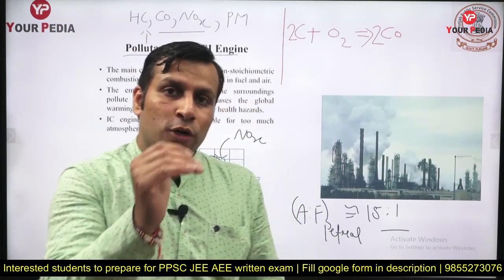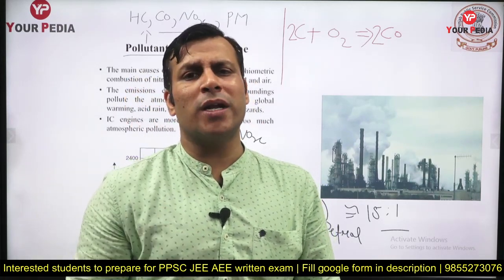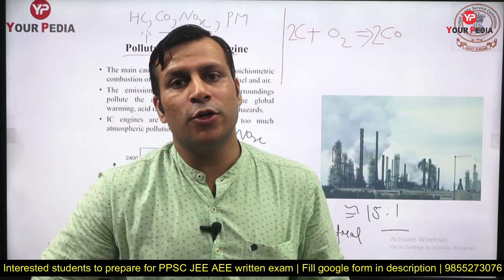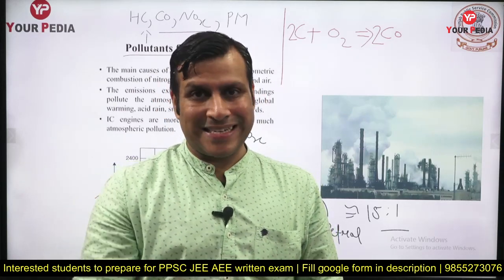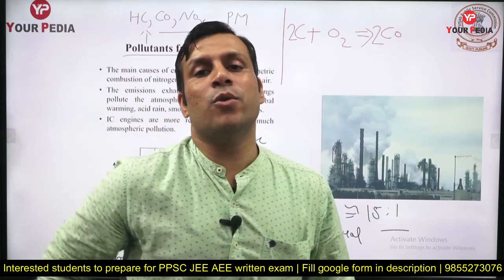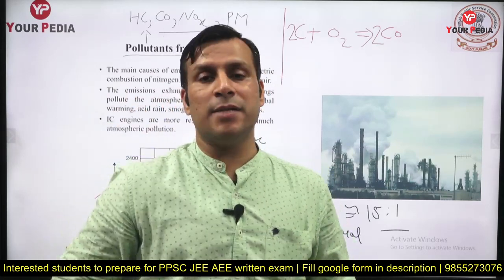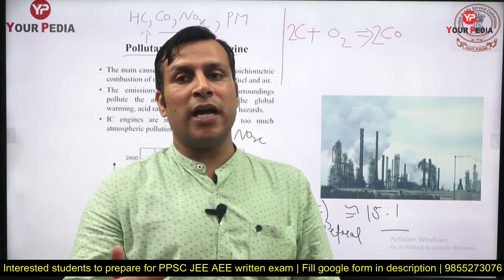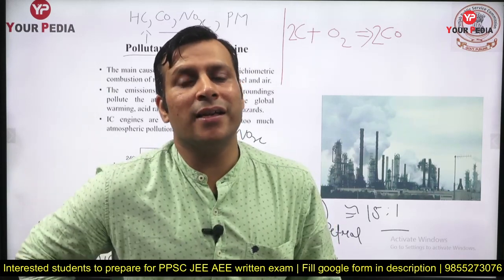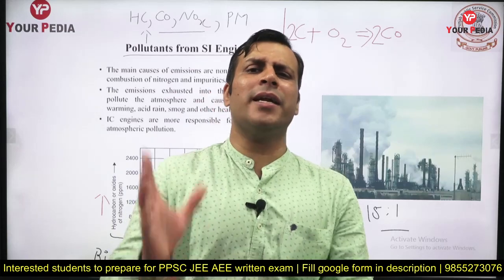So if you are able to reduce the engine temperature, if you are using a lower compression ratio, the NOx emission is going to decrease. For petrol and diesel, the NOx emission is almost similar, but you can observe slightly higher NOx emission in the diesel engine, because diesel engines operate at a high compression ratio, and due to that the temperature and pressure are generally higher in the diesel engine, so NOx formation is slightly more.